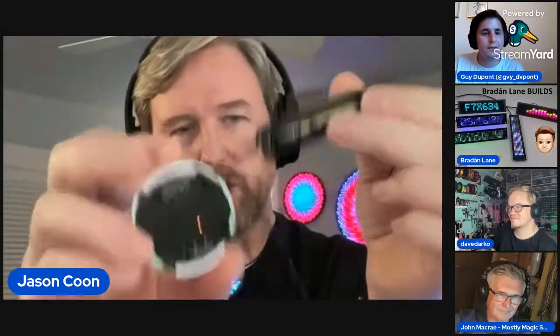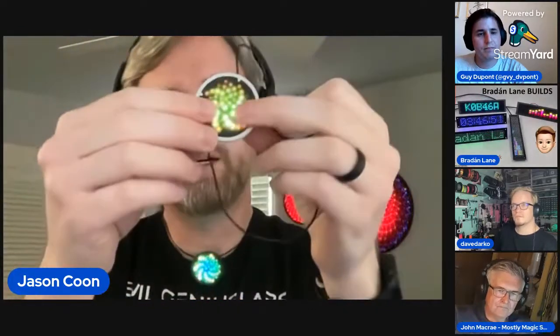And then on the back, both the 3D printed cover and the battery cover, we prototyped, like you were saying, Dave, with our regular FDM printers, but then we sent them off to have them produced with SLS in nylon at reasonable cost at fairly low quantities. And then the bezel, you can see mine has a black bezel, and they're just traditional FDM 3D printed.